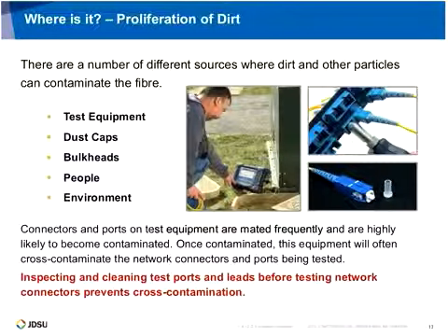So when you unpackage that connector, take the dust cap off, and look at it through a microscope, you can see all sorts of different things that may have developed in there, particularly condensation or mold and such. The good news is that by following some proper best practices, that can easily be removed and dealt with. So it's not a catastrophic problem if you're proactively dealing with it.